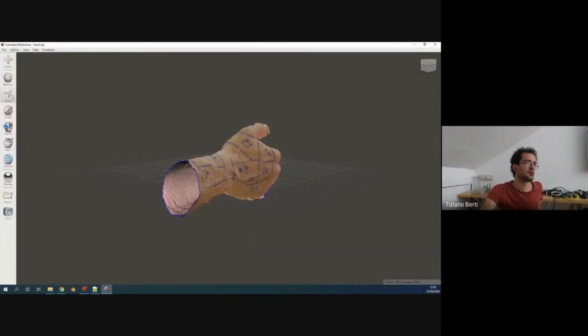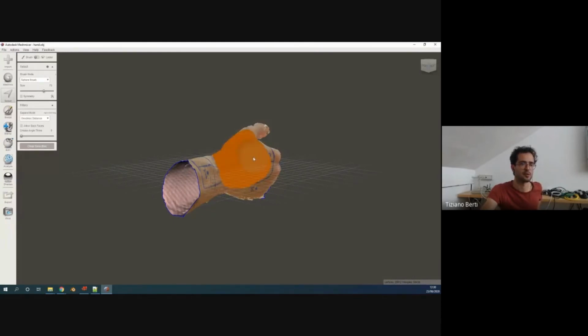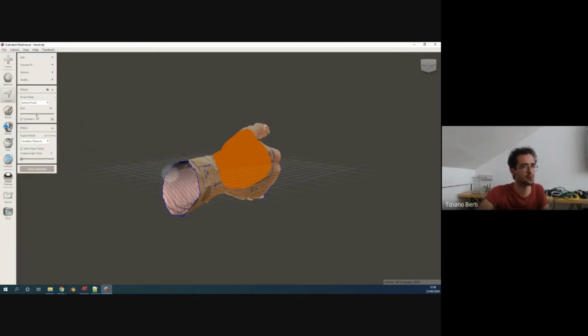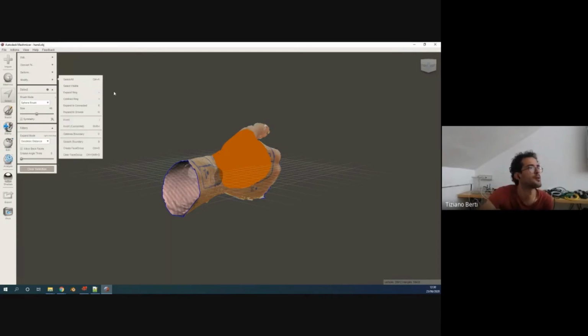This is because all the selection tools, so the size of the selection tool I'm using, are decided by the scale of the first object you import into the scene. So we need to import that back to make changes to the size of the brush and so on.